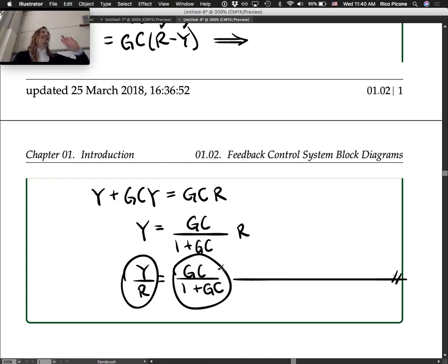Okay. So C is the controller. We can totally do whatever we want to the controller. So notice how C comes in. It'll come into the poles and the zeros. How we change C is going to affect this closed loop performance. And that's how we're going to say, okay, how do we choose C so that some of these response characteristics end up the way we want? And mostly we'll do that by talking about where we put those closed loop poles, and how we affect them based on what C is. So lots to discuss in terms of that.